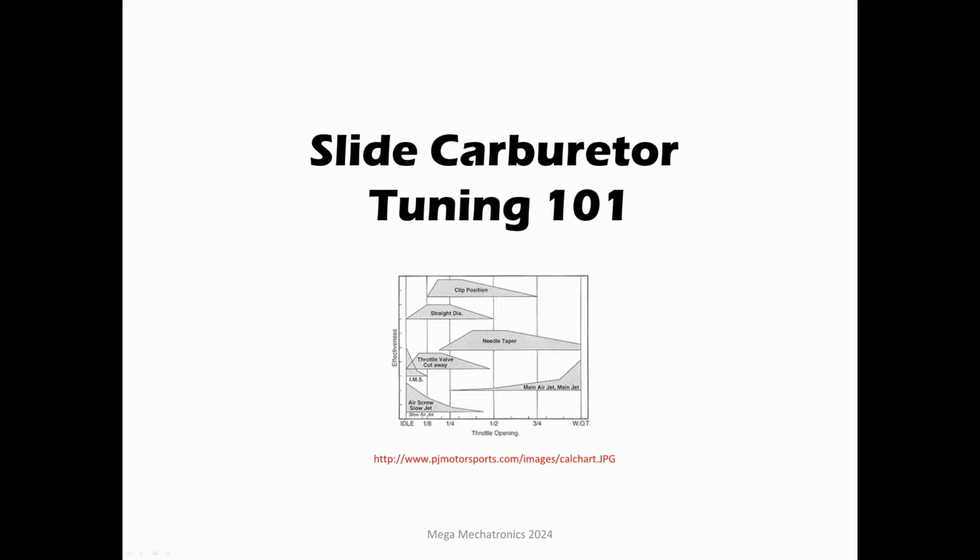And then there's that wideband O2 myth that you're going to kill the wideband instantly, that the wideband is just not even going to work, that you're going to be running it for 5 minutes and it just dies. That is a total lie. Unless, let's say it's running absolutely pig rich, at the edge of just misfiring like crazy, and you run the engine like that for a half hour with the oxygen sensor. What do you expect to happen? That's going to happen to any engine, not just a two-stroke. That's abuse and why you're killing it.